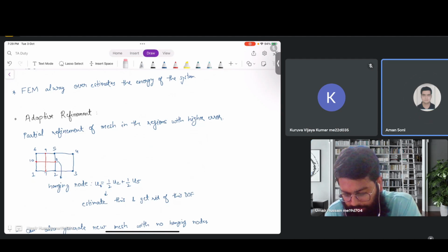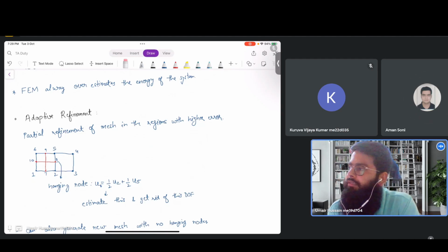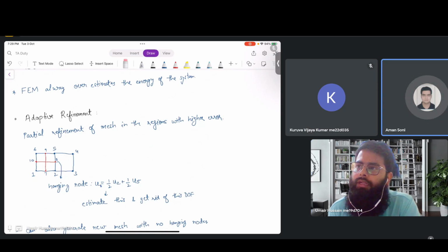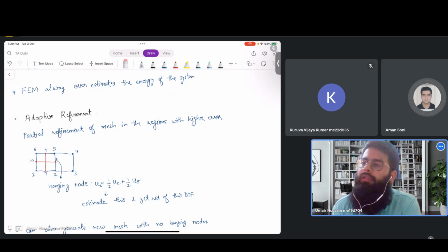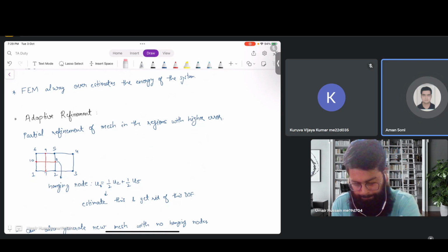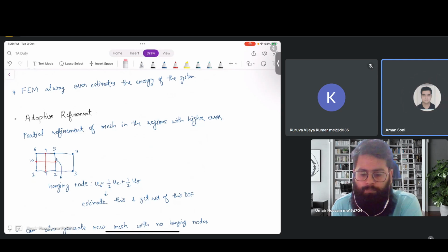I think you might have seen this in some of the solvers or lectures. Yeah, I have seen. Even if we are facing some convergence issue, and what I have observed in my career is that convergence issues arise when you are assigning some non-linear things in your solution, for example some frictional contact or no-separation contact. Then the solver will automatically adjust the stiffness value again and again.